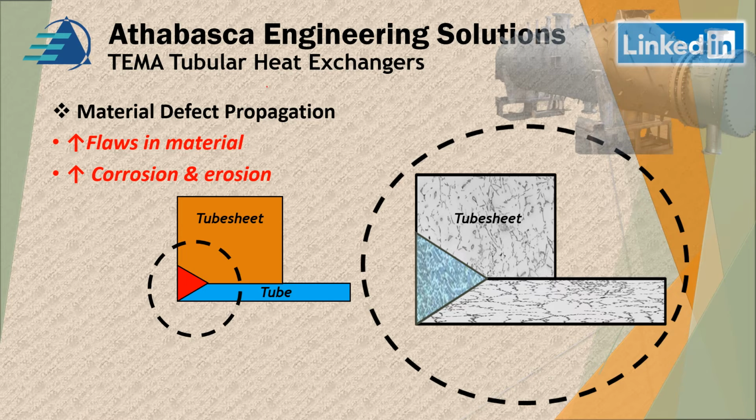So the tube sheet is on the top, the tubes on the bottom, and the welds on the right side. Right where they join on that V is where you're most susceptible to a stress concentration at the root, because you might not have complete penetration of your weld, and there's a stress riser there. We've done some really good videos in the past on fatigue, and there's a lot you can see if you look at our library on the topic.